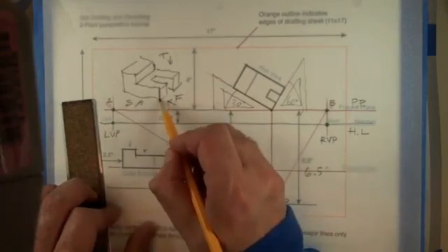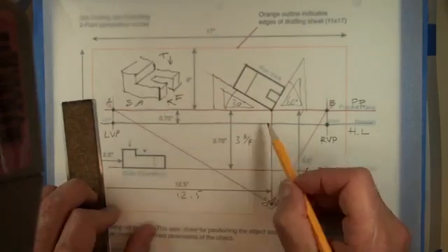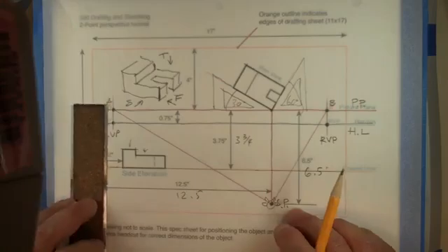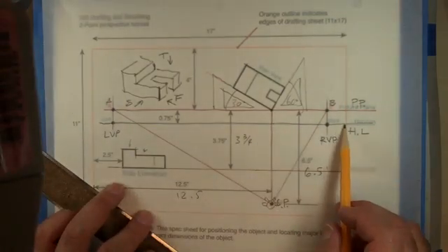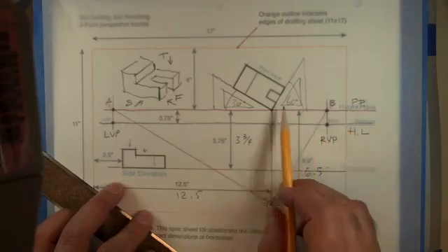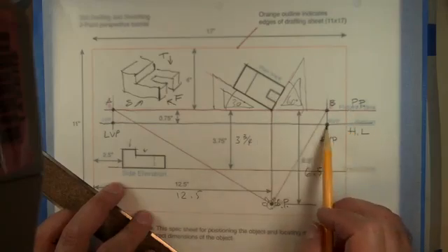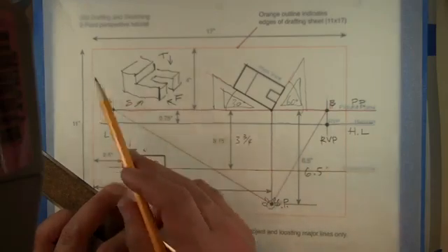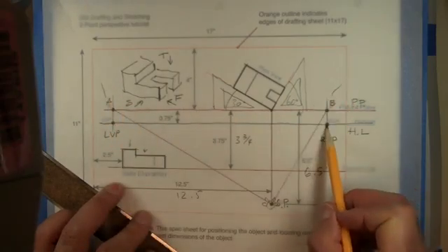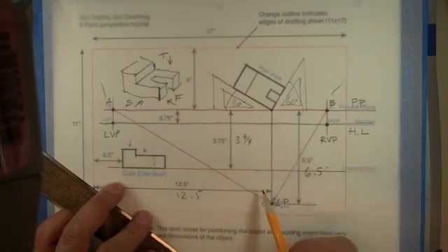Okay, and this is the leading edge. This is the part that's touching the picture plane. Okay, so we have the side elevation, we have the horizon line, we have the picture plane, we have the object, we have established the 2 vanishing points, and like I said, now you kind of have to forget A and B and really focus on the vanishing points, because that's where all the lines will converge.